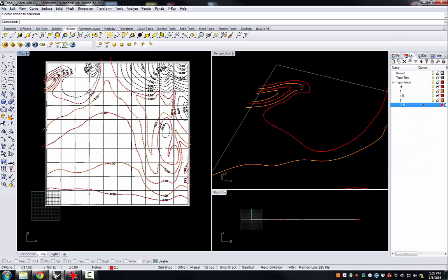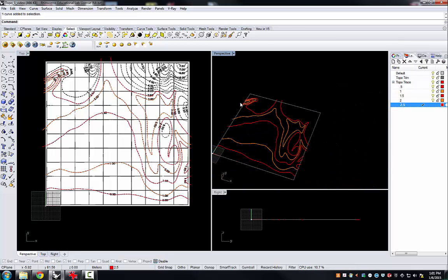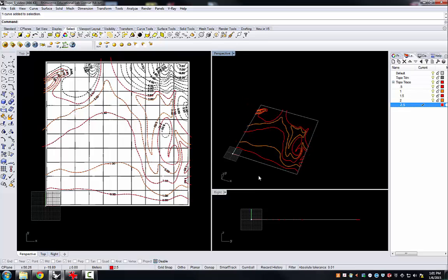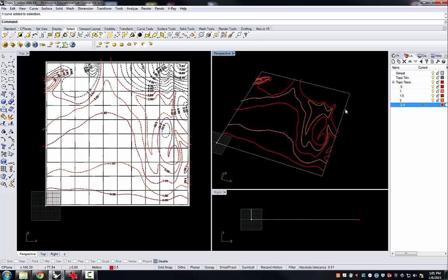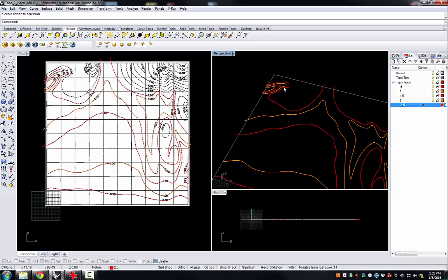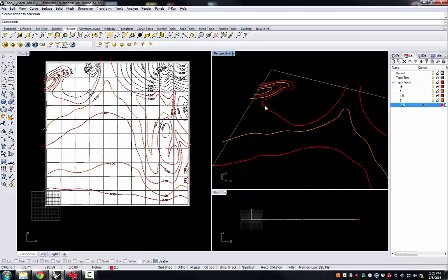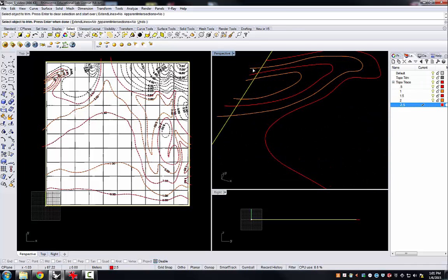So I am not going to go through and click on all of these, but I'm going to move on to one of the next steps after you've done the drawing and trimming, which is to start to move layers vertically to the proper elevation in the Z dimension. Before I do that, I will do a little bit of quick trimming here. I'll just type in trim, and I'll zoom in and just zap through trimming a series of these. It won't take very long.